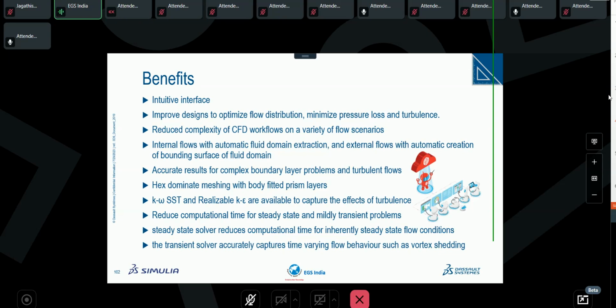There are specific turbulence models available in our fluid capability, called K omega and K epsilon. These can be used either for internal flow or external flow, depending upon the Reynolds number or the problem that you are going to solve; this particular turbulence model will be efficient to go with. And we have a specialized turbulence model called Spalart Allmaras, with which you can solve any kind of aerodynamic problem. Those aerodynamically complex problems can also be handled with this fluid domain.